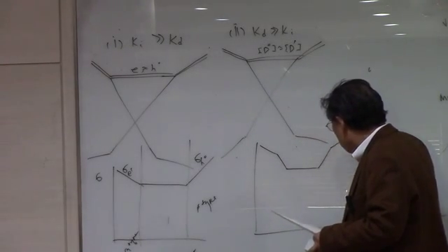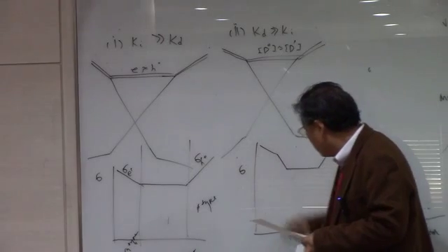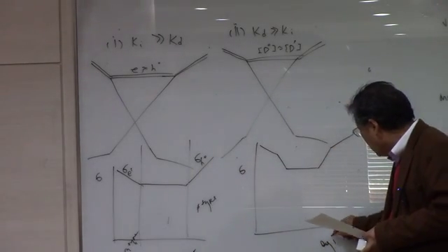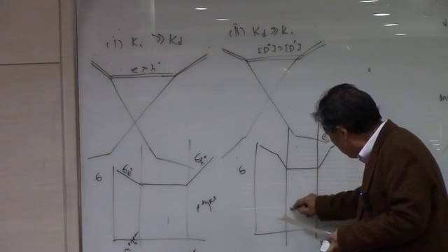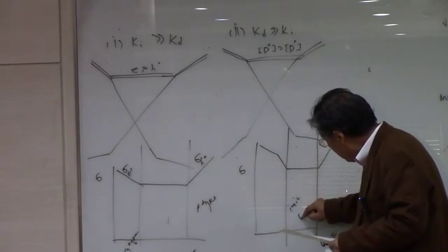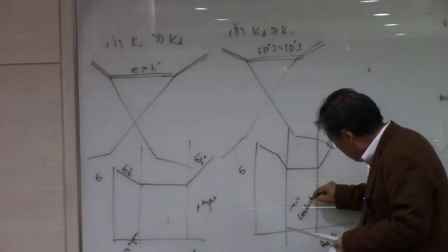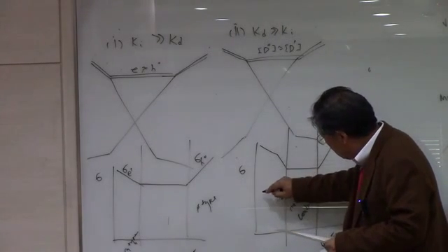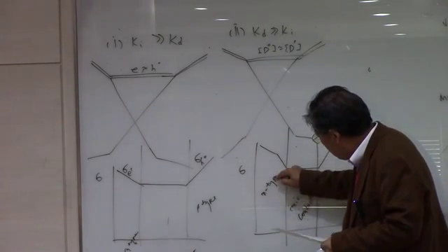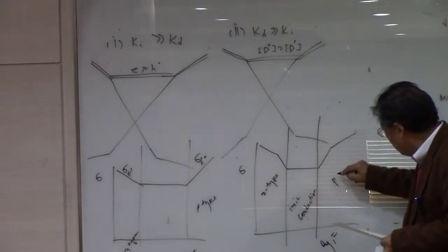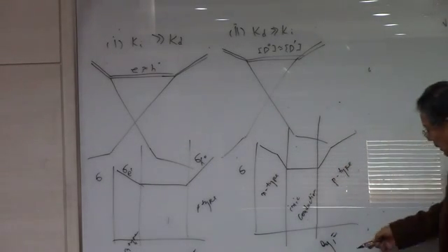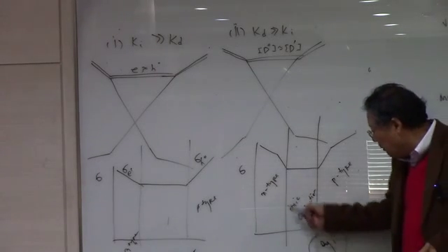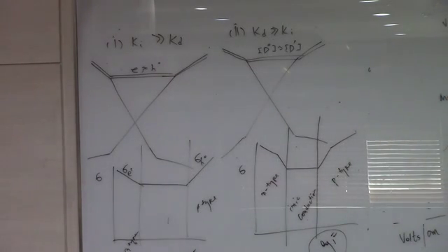Now, if we have this situation, then we are going to have something like this that you have seen before, conductivity and log F. And only at this part is going to be ionic conduction. And this part is going to be N-type, and this part is going to be the P-type. So a material can change its type depending on the environment.